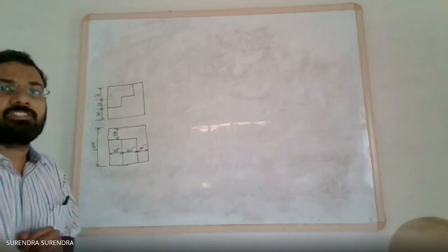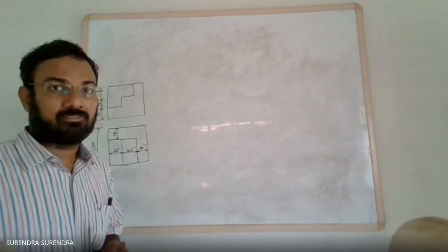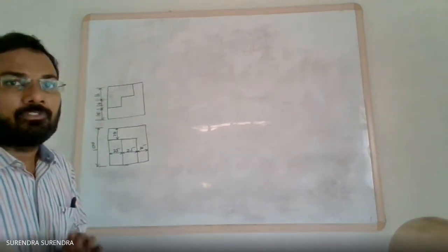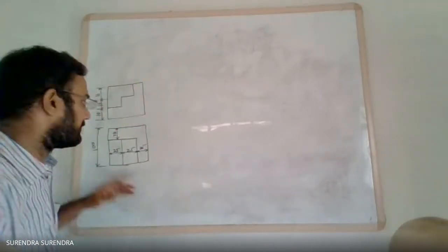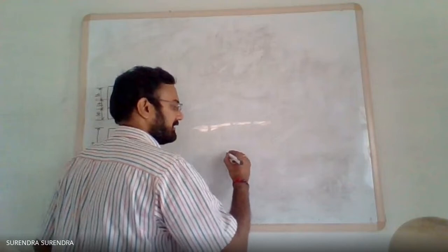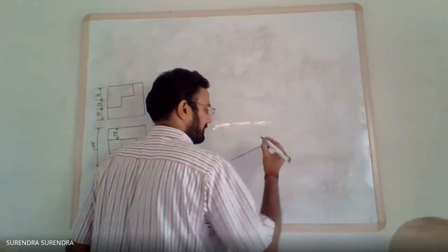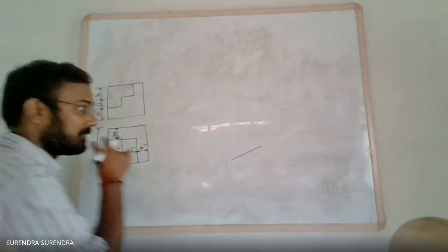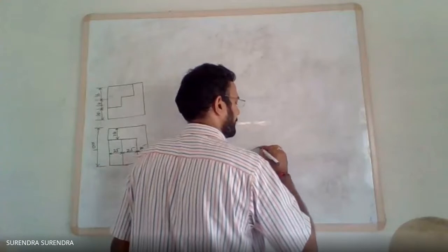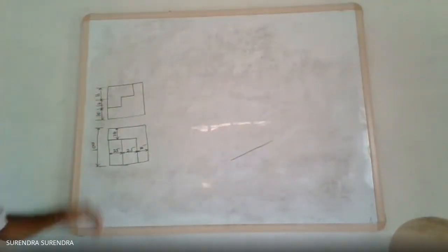First let us draw the prism shape outline with these dimensions. With the 2H pencil, construct the outline. The length axis is drawn along 30 degrees inclination. What is the length? 75. Height equal to 48.